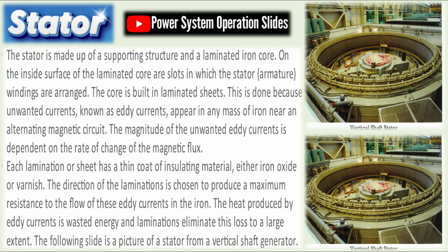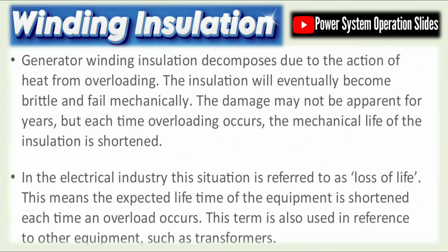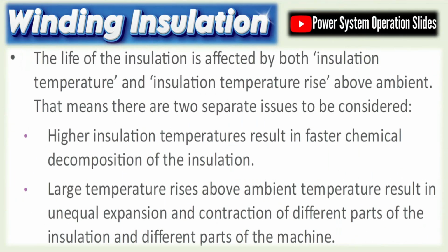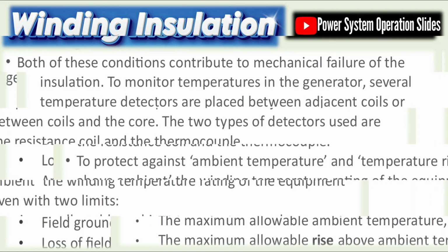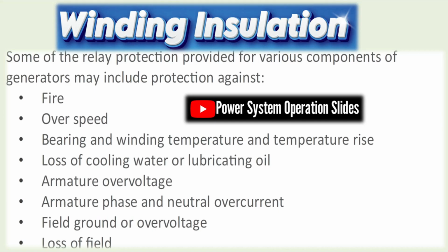Gas turbines operate on the Brayton cycle. They are compact, capable of fast startup, and widely used in peaking plants and aircraft. In power generation, they are often combined with steam turbines in CCGT configurations for enhanced efficiency. Hydraulic turbines include Pelton, Francis, and Kaplan types, each suited to different head and flow conditions. These turbines convert the potential and kinetic energy of water into mechanical energy, which is ideal for both base load and peak load applications depending on reservoir capacity.